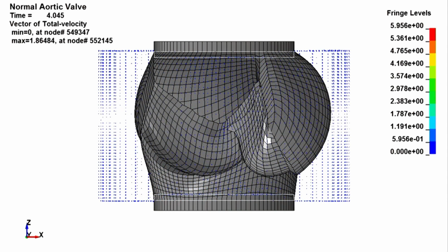So it's a fluid structure interaction, shell element, Newtonian fluid, that 4 baskets. We fix the bottom because the rings are usually fixed. Okay, they don't move. And this gentleman who asked the question, good question. So we know from understanding the biomechanics where you have to fix it and so on. In fact, we have done the complete aorta and other cases. So what came out of this? Why is it that this study is interesting, and why did we do it?